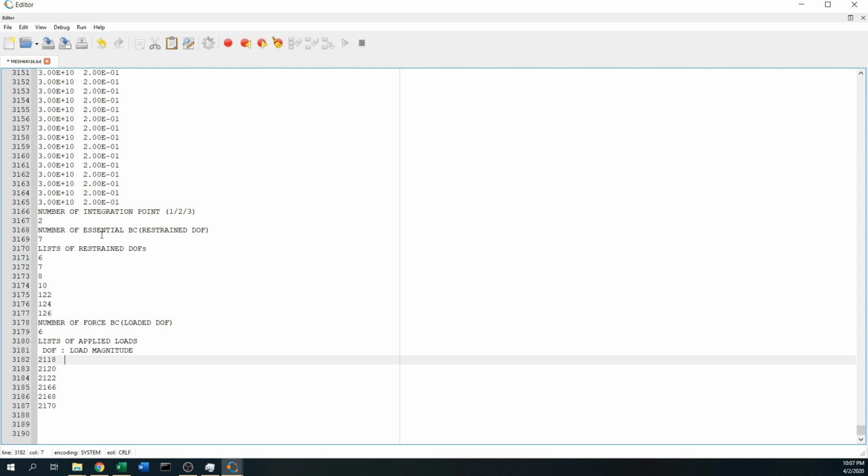Steel was placed over there already, but I think I have too much steel then. If now the steel and concrete are having the same width. This is a plane problem, so we are dealing with just 1 unit thickness, and that 1 unit thickness is the same for concrete and steel.